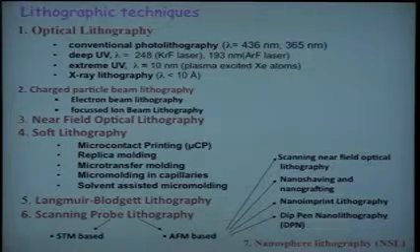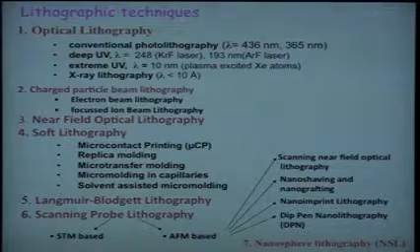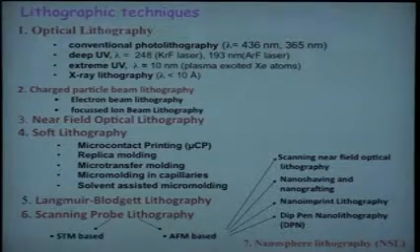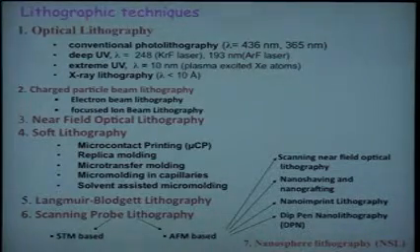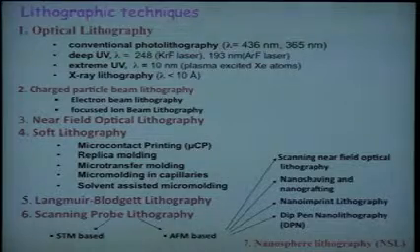And then on soft lithography, there are in fact a bunch of techniques. I have only listed out a few of them. When it comes to soft, it is all about elastomers, creating stamps, and then creating patterns. And you can't be using the common rubber, because in common rubber the particle size is of the order of a few microns, and it doesn't permit you to stamp something. You won't get the resolution you want in terms of nanometers.